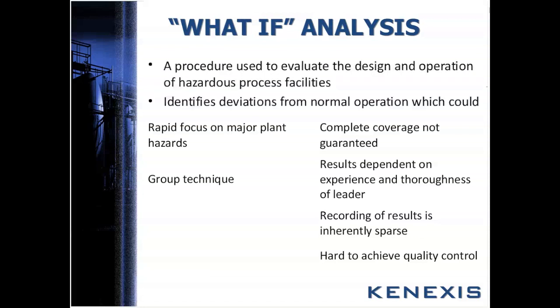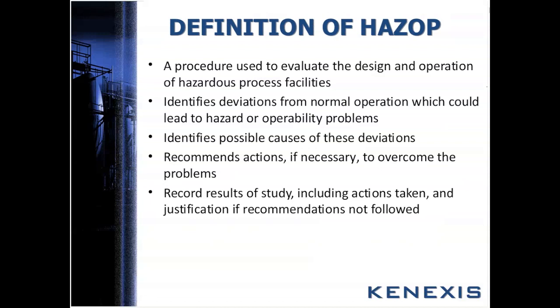Okay. So let's talk about HAZOP a little bit, because HAZOP's the workhorse of the industry. Remember, it's used to evaluate the design and operation of hazardous process facilities. It's about the only good technique I know of that does both of these operations, the design and operation, because that's where the design marries to the procedures and how operators really run the plant. So HAZOP typically identifies deviations, looks at the causes of those deviations, recommends actions, and records recommendations.